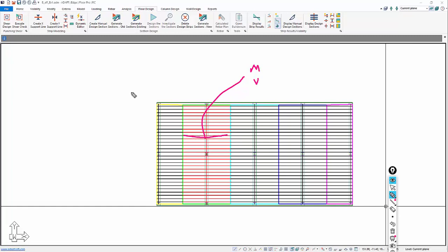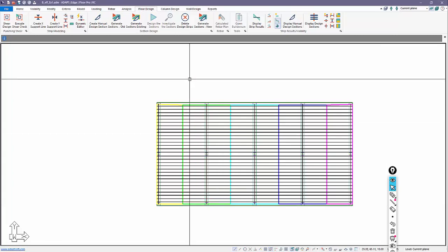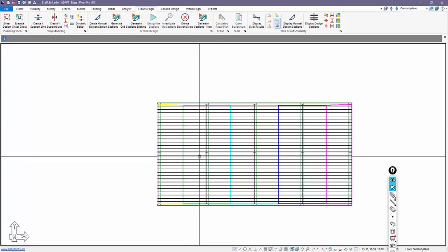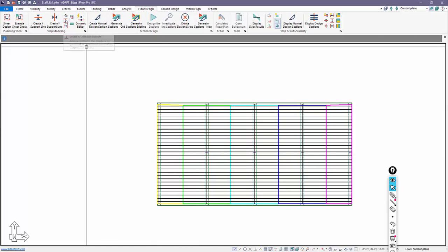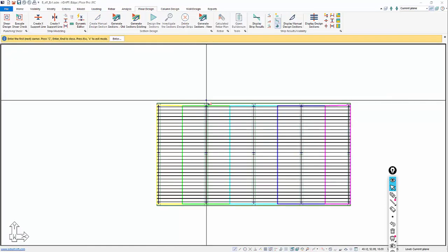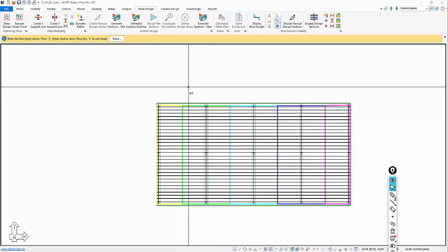So this section that you see, a T section, this B dimension here is equal to what is actually modeled in the system. Okay, if we say, well, we want to somehow modify the width of that strip so that it equates to some effective flange, I could use splitters. I could go in and say, well, let's just create a splitter. I would have to have some way to dimension this to either side of the beam.